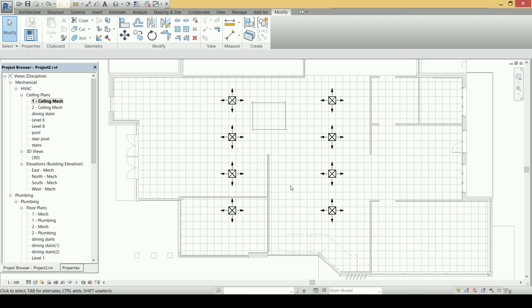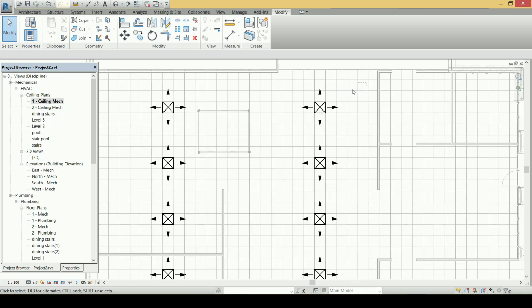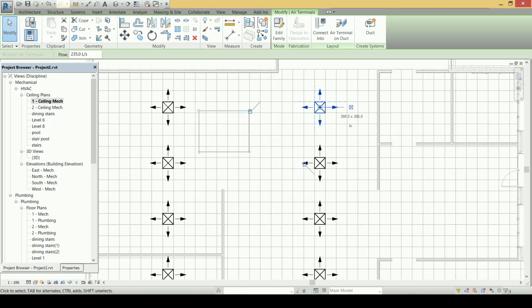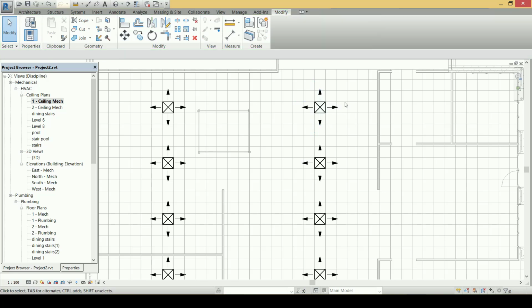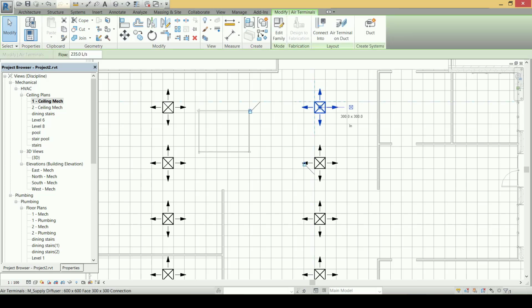But you can tell me now, what is the difference between the right selection method and the left selection method? Here I say that when I drag from the right to left and I select the object, the whole object will be selected even if I didn't select the whole object. So let's try it again. Here I have selected only a part of that object, or I have selected it partially, and despite that, the whole object has been selected. So for the left selection method, you can select the whole object by selecting only a part of it.